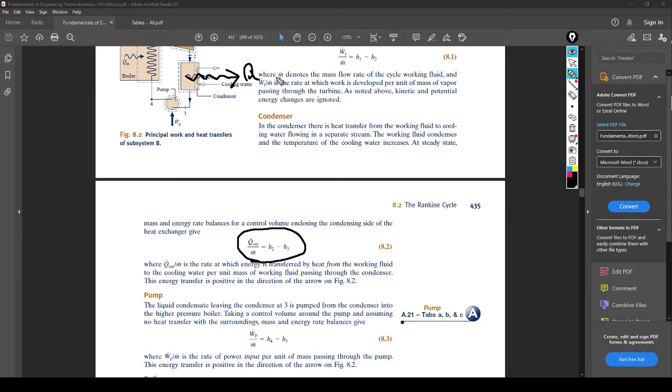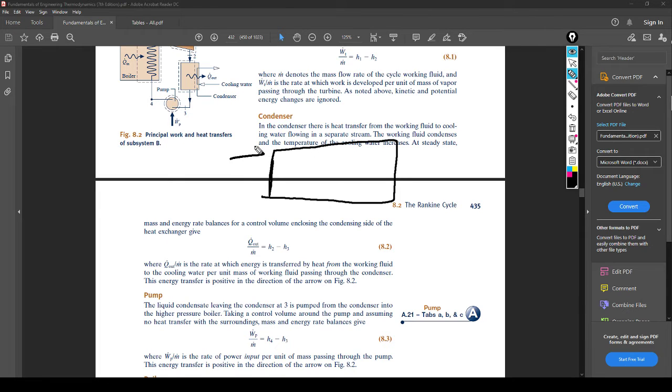And it's not like it's just leaving, right? It's not like just flowing into the ether. It's leaving in the form of water, running through this stream. So don't think of a condenser, and I know we've done a condenser question, but don't think of a condenser as anything different than a heat exchanger. That's all it is. So those heat exchanger questions where water comes in here and leaves here, comes in here and leaves here, at these conditions, this is what that is.